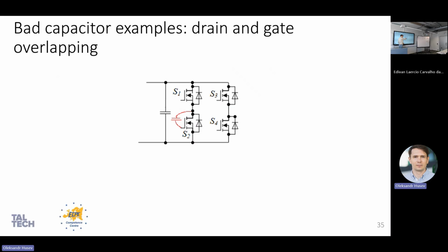Because of the variation or change in voltage, when it's supposed to be not conducting, or it was conducting, so it's zero, but then suddenly you switch off this transistor, which means that voltage rises up to the nominal DC-link voltage, but through this capacitive connection, you will have voltage across your gate signal. And you have here, for example, 350, but here you have a GaN transistor, which has a nominal 6 volts, and at 9 volts it will be killed. And you have some delta V, right, which may kill your transistor by just very bad design.